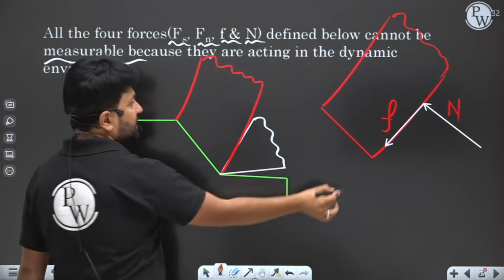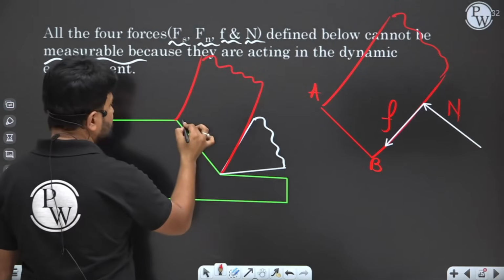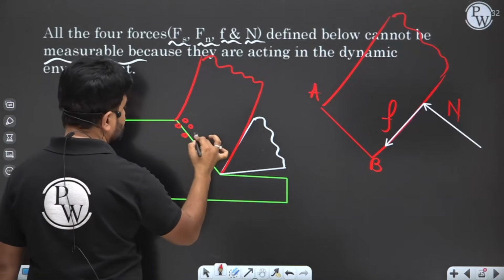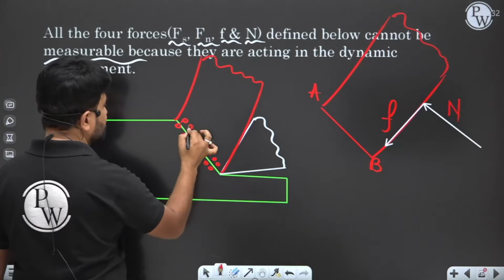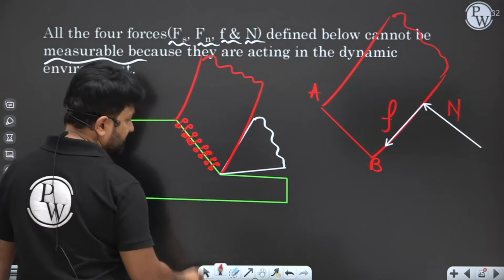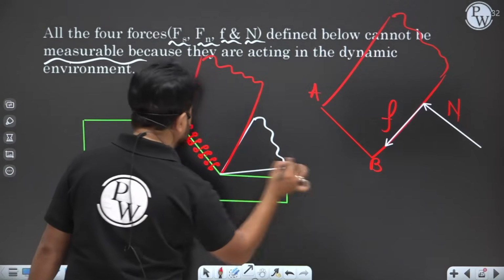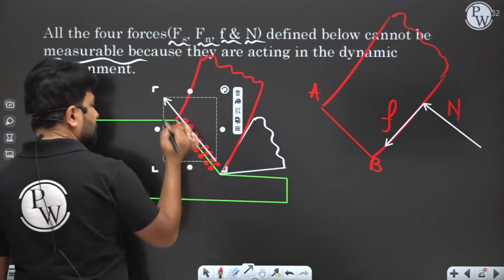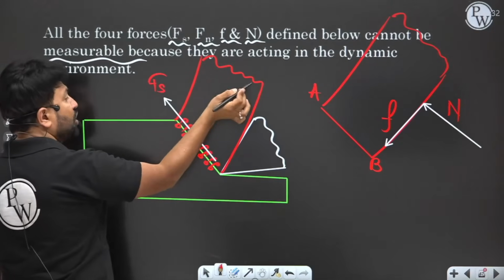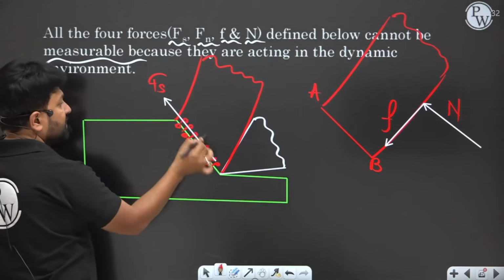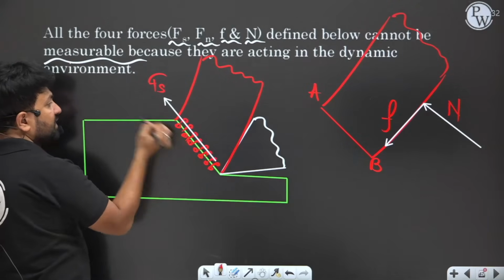Now, in this shear plane, AB, because of the tool, you want to break this crystal structure. So you apply the cutting force, and because of that cutting force, a shear force is acting on the chip, which is going to break down the bond connecting it with the workpiece.